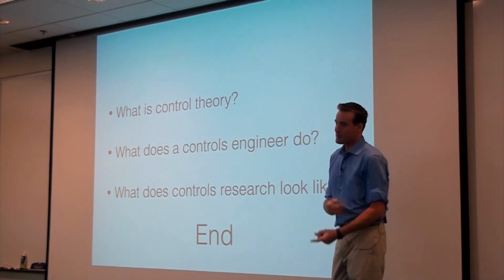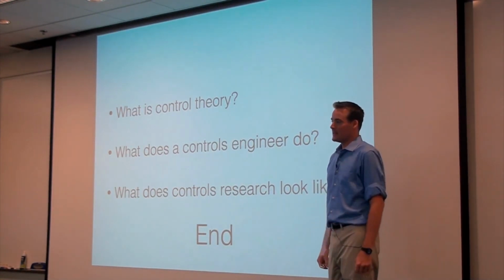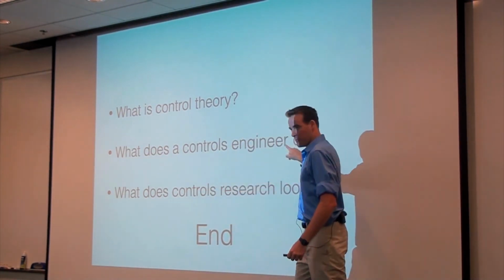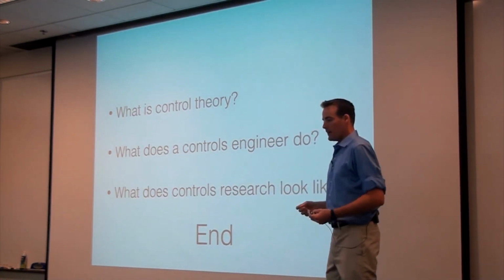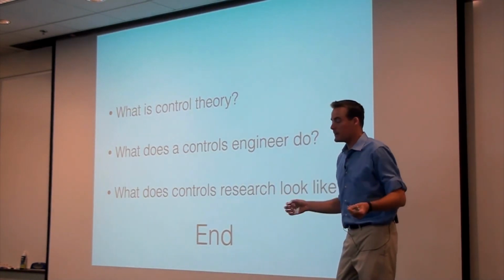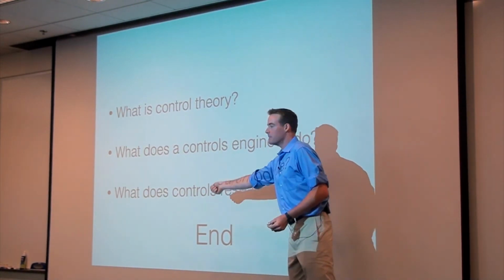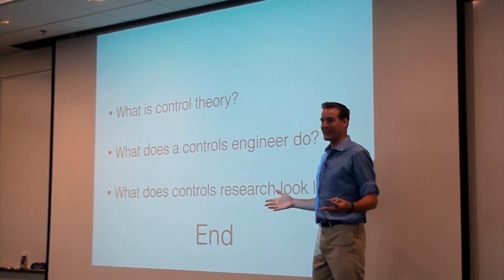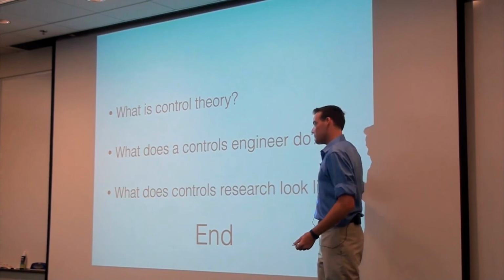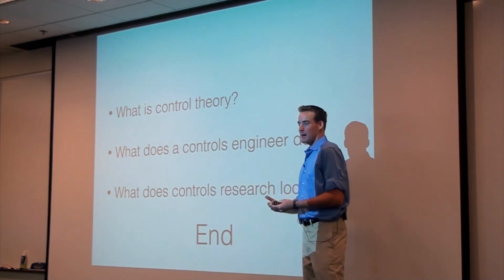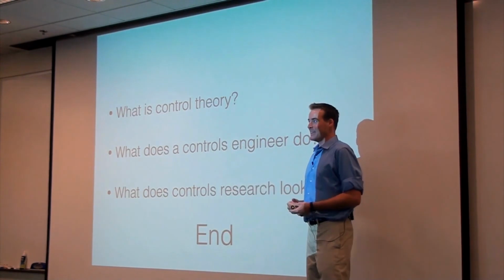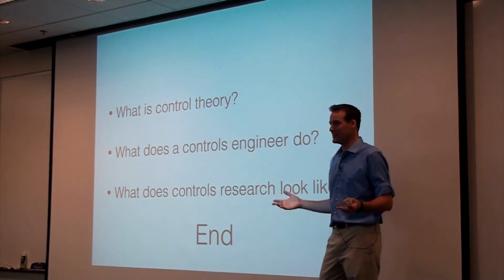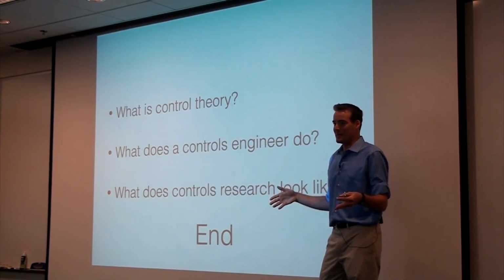Oh, my work is kind of boring compared to these guys, but it's called limited bandwidth control. So remember this negative feedback control loop with the pendulum. The assumption in the undergrad theory is that you have a continuous stream of infinite precision real numbers being fed back to a controller. That makes life easy because you can analyze it nicely that way. But in reality, you do not have an infinitely fast stream of them, and you don't have infinite precision. So you have bandwidth limitations, and that's the study. My work is how you can extend the theory to accommodate limited bandwidth.